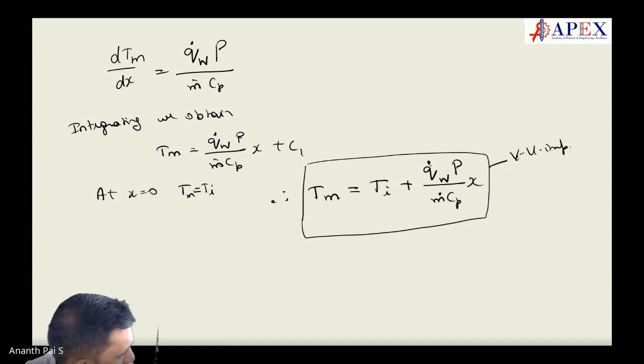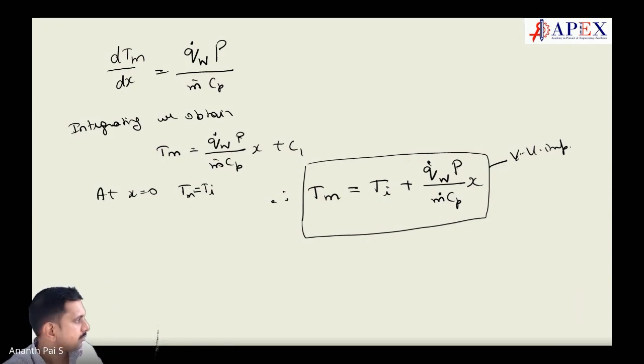So in this equation, Tm equal to Tw? Who said that? Because dTm by dx equal to dTw by dx. Can we put it in the same? No. Why not? The boundary condition is different. Correct? So what will happen? There is nothing called Tm here. We cannot do Tm at all. It is the T of the wall only.